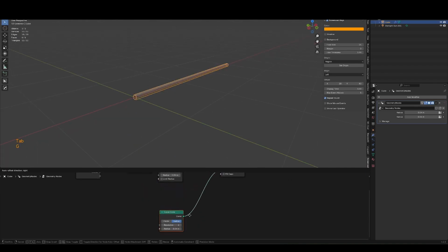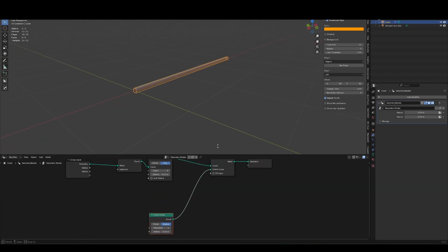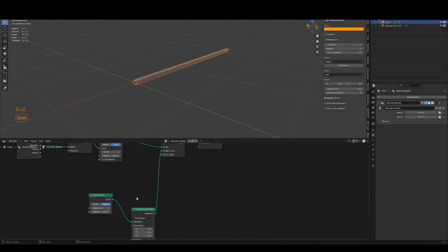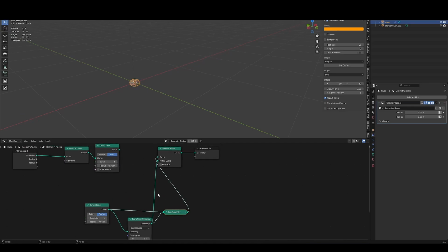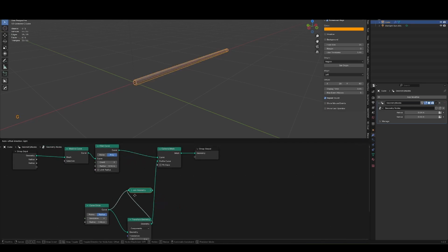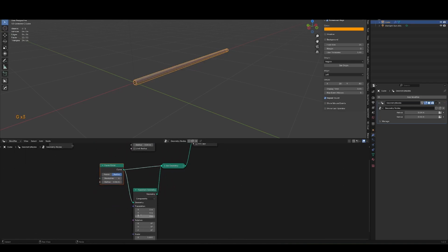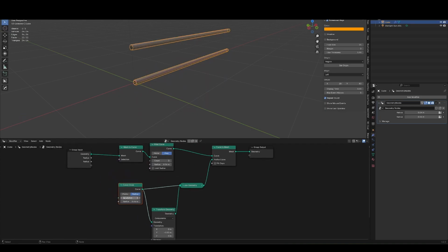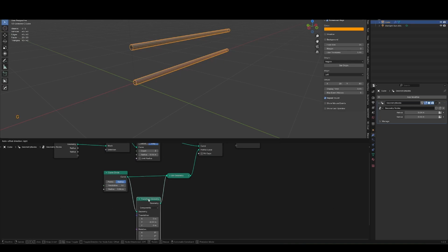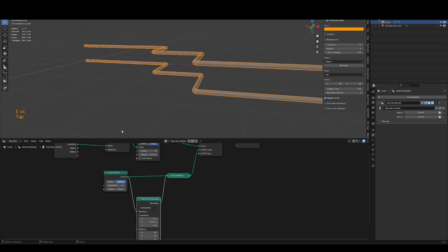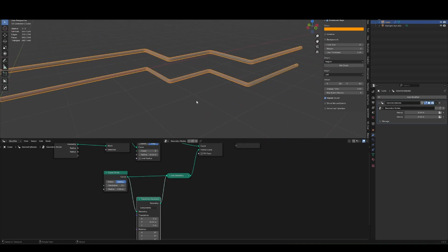So what I want to do is repeat that circle. So I'll run a transform geometry, and then I'll hold Control Shift and drag my middle mouse button to join geometry. I'm going to fix up this curve into the right socket, fix up this into the right socket. So this is actually running 2 circles now, so if I offset this, you'll see that. It means I can still control the resolution, but it's duplicating this in a different position. And now what I can do is run that wherever I like, and it's got 2. So we're getting there already.